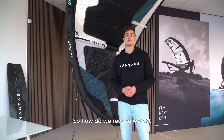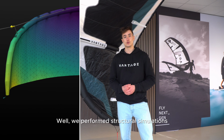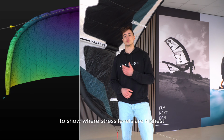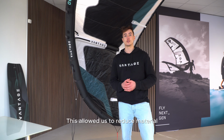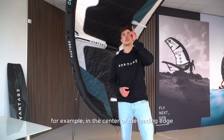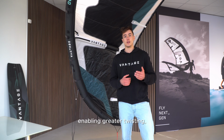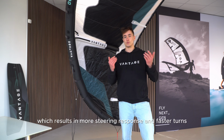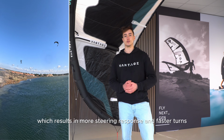So, how did we lose weight then with structural optimization? Well, we performed structural simulations to showcase where the stress levels are the highest and where deformation takes place. This allowed us to reduce material in places where it isn't needed. For example, in the center of the leading edge. There we reduced the leading edge diameter, enabling greater twisting, resulting in more steering response and faster turns.